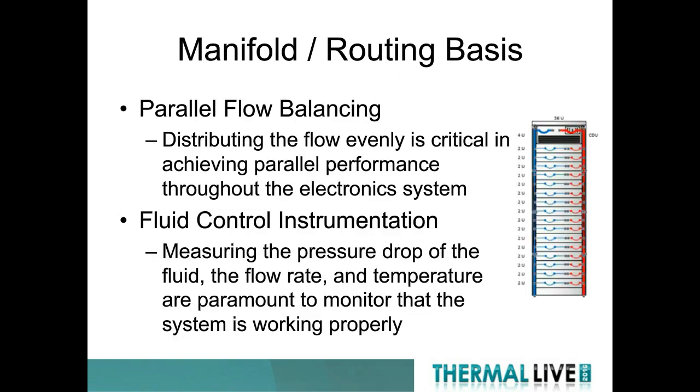The next basis is the manifold and routing. What's important here is that typically the manifold will distribute the main flow into all of these device and interconnect basis. The key is that we have to have parallel flow balancing. Distributing the flow evenly is critical to achieve parallel performance throughout the electronic system.